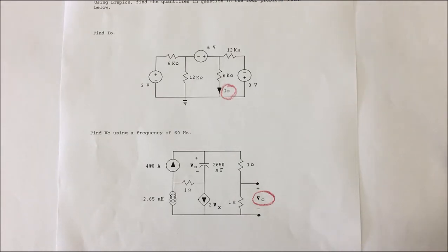Anytime that you explore some new software, you probably want to have a baseline. So I highly recommend, I think it's imperative, that you work these problems by hand so you know whether you're getting the right answer or not. Many times when I've been thinking about turning something over to a computer, I take a test problem, I work it by hand, and then I use the computer and see if I get the same answer. I think that's important. Not that the computer would be wrong, although sometimes computer programs are wrong. It's just a test to make sure that the same inputs and assumptions that you use are the same ones that the computer uses.